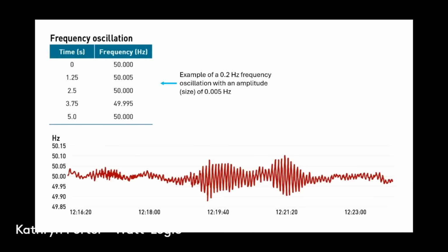So first of all, the system operator detected frequency oscillations at a low frequency of 0.2 Hertz. So this is a slow deviation that's overlaid on top of the 50 Hertz grid frequency. And this deviation completed a cycle every 5 seconds. And at the same time, voltage dropped and also became unstable. It started to oscillate. So the frequency and voltage oscillations shared a common cause, but they don't cause each other. In the same way that sunshine will cause plants to grow and it'll cause people to get sunburn, plants growing doesn't give people sunburn and vice versa. They share this common cause, but they don't cause each other.